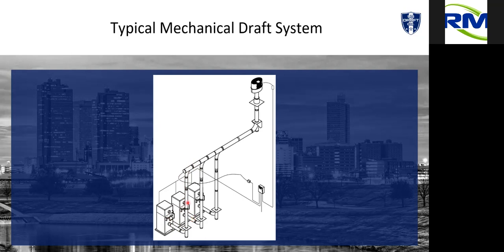But now the master controller says, well, wait a minute, I need a second boiler. I've lost number 1, so let's turn on boiler number 3. So it does its pre-purge. Again, creates another blockage in the common, shuts off the running number 2 boiler. And all of a sudden you have these cycling boilers that can't get going because the second boiler, or the boiler next to it, is starting to affect that.